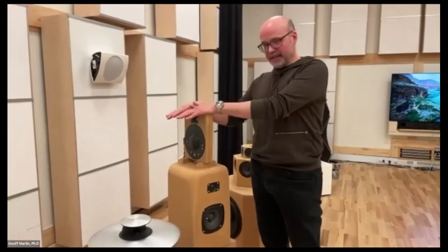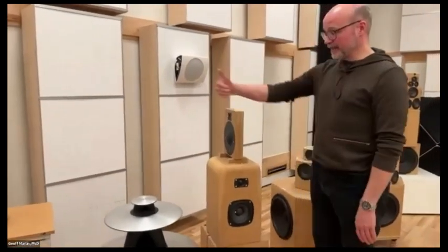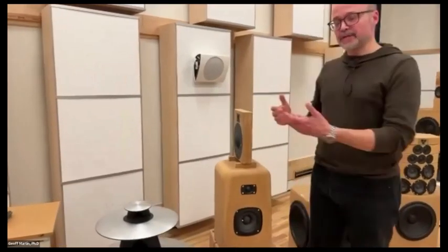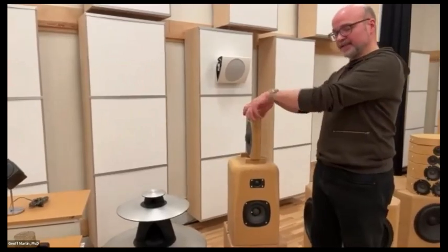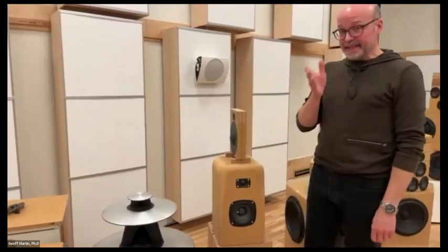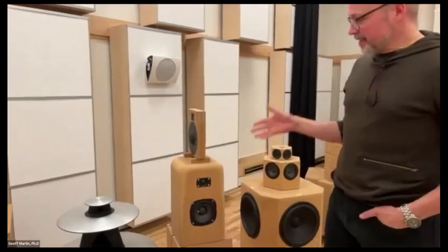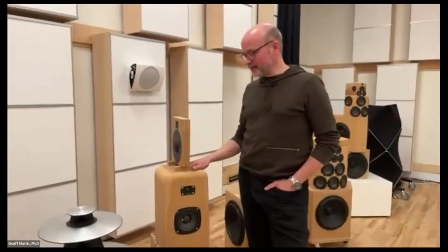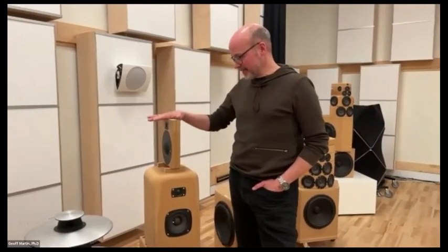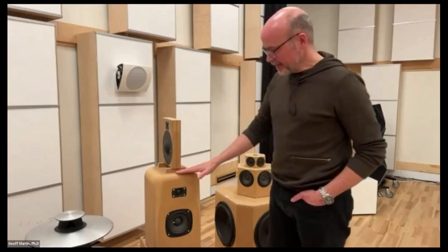So all the dipole is doing is putting out energy to fill up that dip. But because it's a dipole and moving this way, in effect, then in theory, there's nothing going out the front. So what we can do is use the dipole to fill up the power response without affecting the on-axis response. That was the concept. If we measure this speaker, then the concept works. If we put this speaker in a very diffuse field, the concept also works. We get a nice smooth power response because this has fixed the problem, and we get a nice on-axis response because that's been behaving all along.